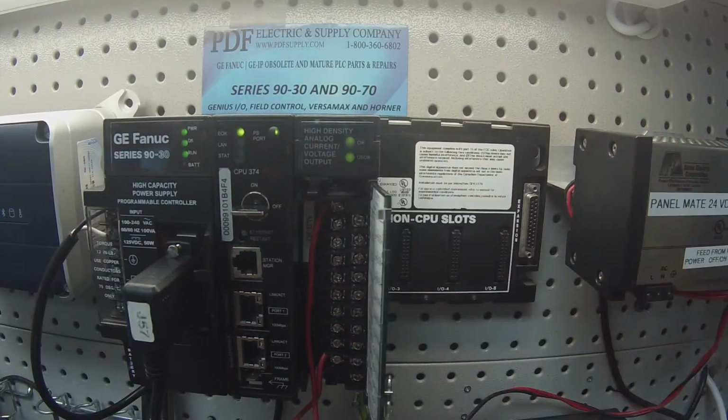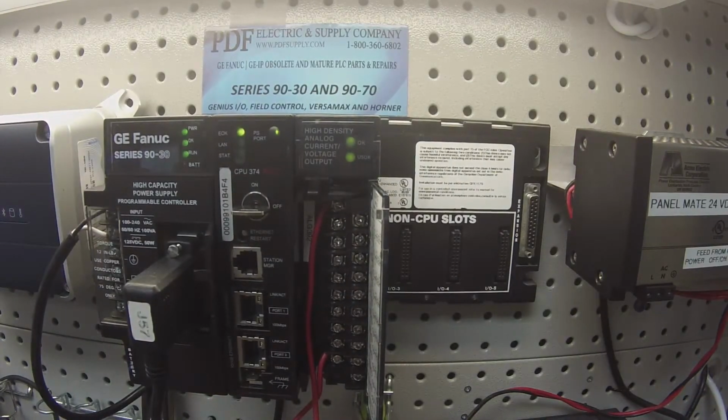So what I'm doing there is I'm making sure that it's not a failed card, because what we normally see is that if a card fails, more often than not, it fails at full value. In other words, no matter what value I put in the output table, it's always going to read 10 volts for some reason. So you want to make sure that you scale down however you see fit to do it. My way is just by doing it 32,000, 16,000, 8,000, and just descending on each channel to make sure that they have their full range of value, since it is an analog output.